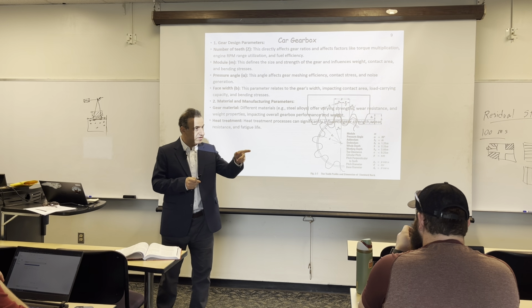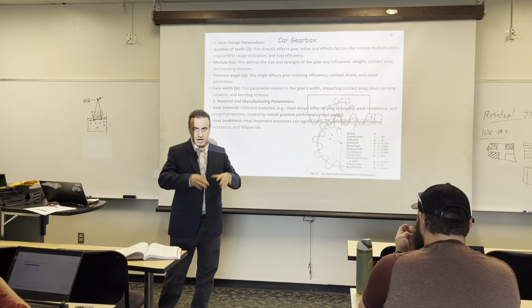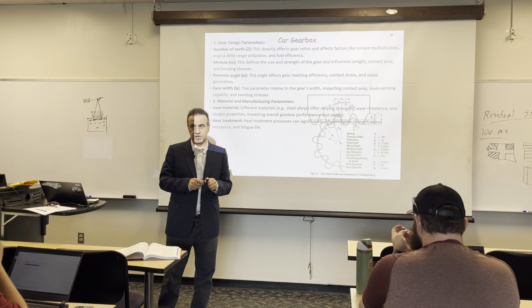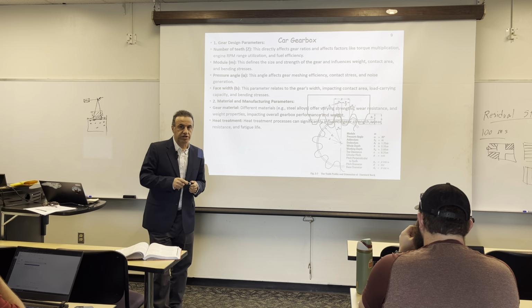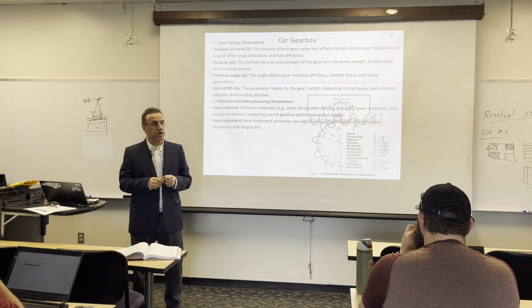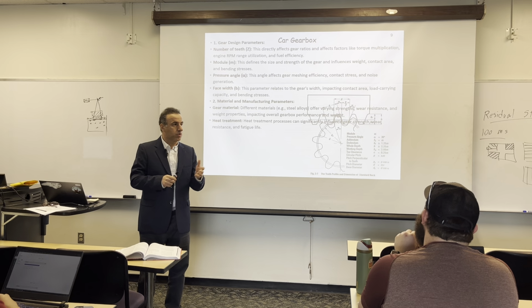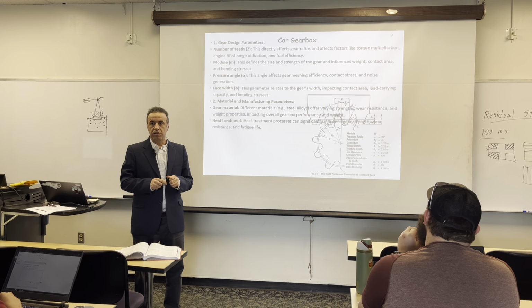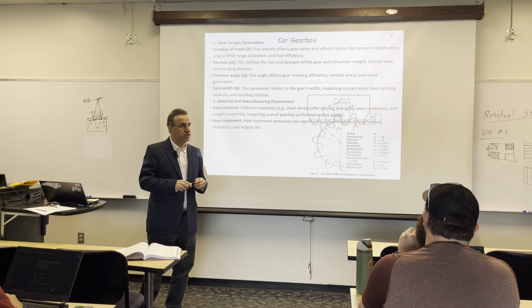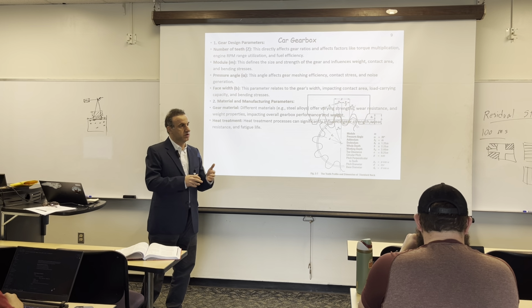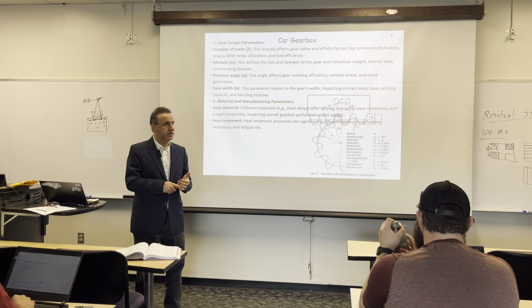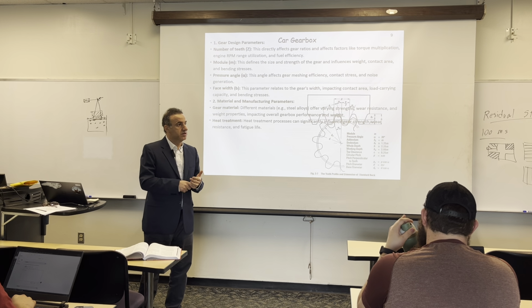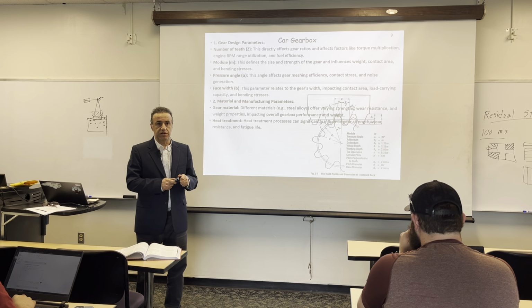And even stainless steel has a lot of categories in there. Whether it is austenitic, when you look at the microstructure, those alloying elements, chromium, nickel, these alloying elements change the property, change their category. For example, we may have austenitic stainless steel. We can have ferritic stainless steel, right?